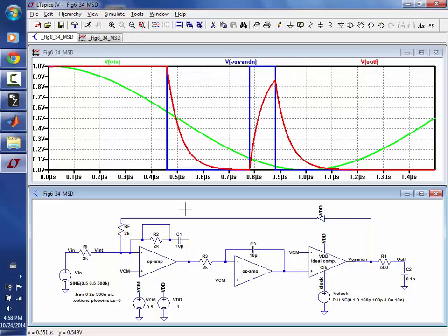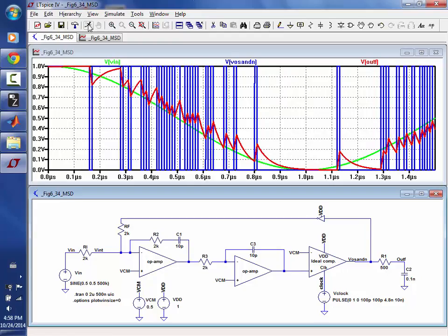So I shorted out the resistor so that my poles are right on the y-axis. When I put the resistor back in there and hit run, it starts to work again. It moves the poles away from the right half plane. Are there any questions on that? Because it didn't follow the input. Yeah, and it went to the rails.